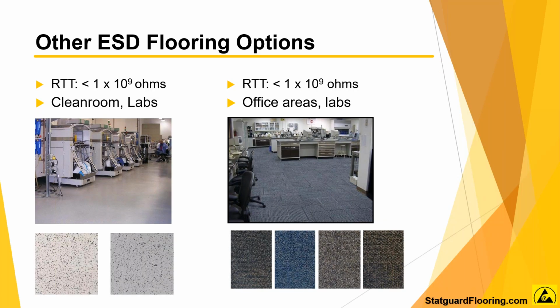Other ESD flooring options include rubber. This material is very durable, offers comfort and sound deadening. Modular copper tiles provide comfort and easy repairs. This product is installed with a releasable conductive adhesive, which makes it easier to replace when needed. It is suitable for installations in IT rooms, labs, 911 rooms, FAA control centers, etc. The rubber and copper material has a resistance of less than 10^9 ohms.